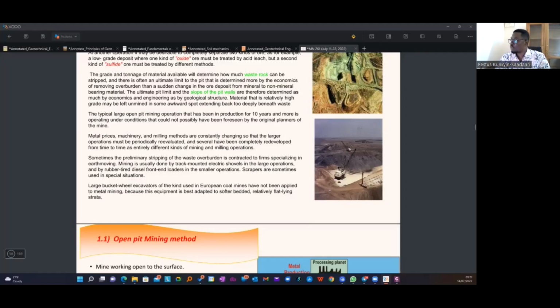You know, we went through the processes, and so we start proper mining from development. Then we go to exploitation. So at that stage, when we are beginning to mine, the mine engineers or the mine planners will come up and say that based on the economics, the current gold price, and how much it costs to start our business, I think we can only go this deep. And when we get to know that, it helps us define how we are going to take the overall pit slope angle.